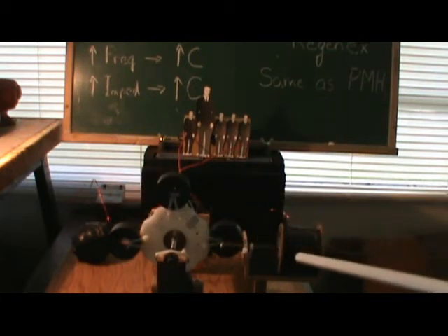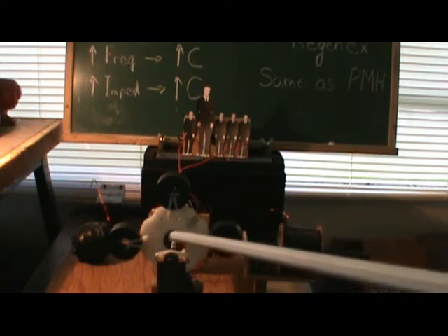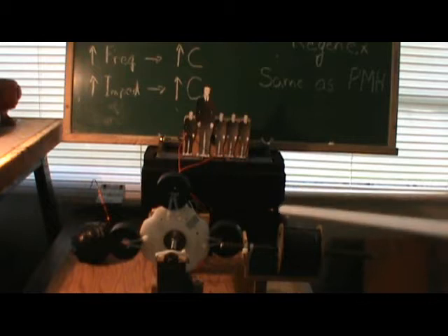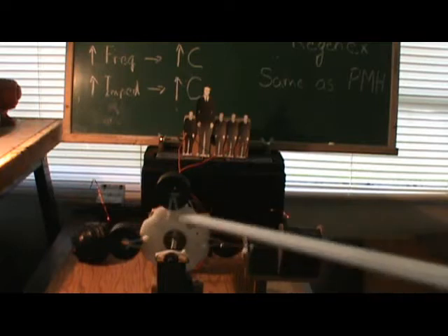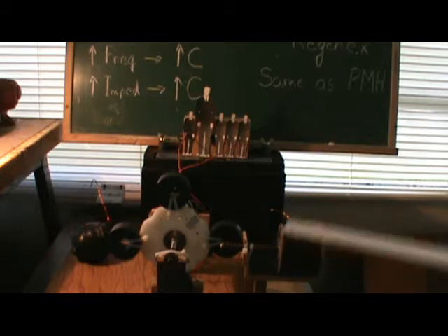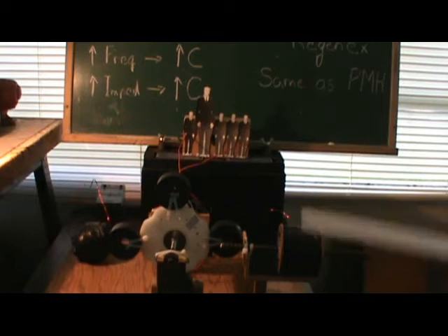So then I'm going to demonstrate two sizes of wire in the same position, on the same core. And we're going to look at the RPM. Now if you move these coils up and down the bar, it's going to change the current flowing in the wire, which is going to change things. But in this video I don't want to get into that. I'm going to keep these coils, and now they're basically the same shape. They're each a kilogram of copper. This one's 14-ish gauge. This is definitely 22 gauge, much thinner.